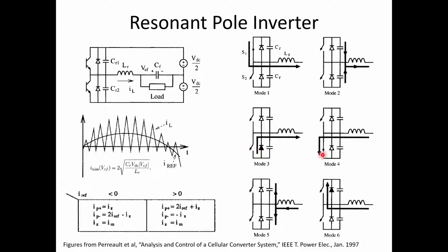I will turn on the bottom switch, and what will eventually happen is, because the current's slowing down, the inductor current will reverse, and now I'll be building up negative current in the inductor. Okay? I'm going to let this negative current build up to a particular minimum value, I'll call that IP minus, for example. And eventually, I can turn off this bottom switch, and the pre-charge current in this inductor is going to resonate with these two capacitors again. I turn off the bottom switch with 0 voltage switching because of the capacitors.